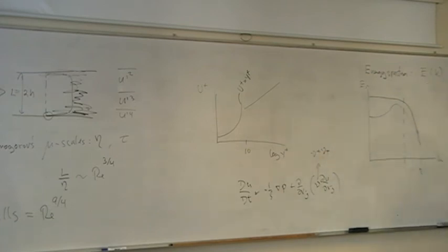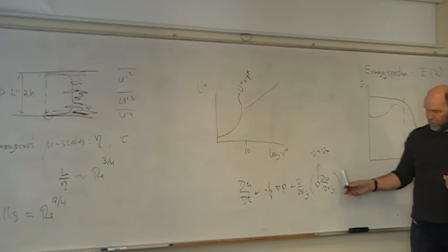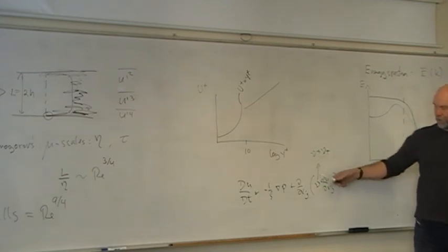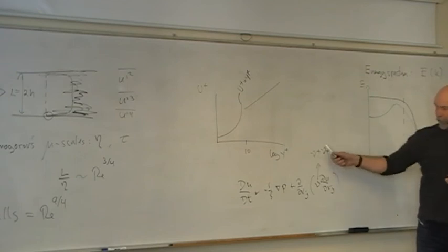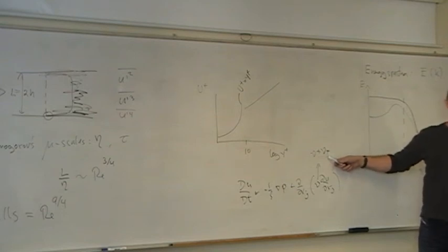So again, you adjust the viscosity using a large eddy turbulent viscosity, and then actually you cheat, you sort of increase the viscosity so that the turbulent scale is not so violent anymore. But at least now you have a number for this function, so you know your cheat can be documented and understood as a turbulent quantity.